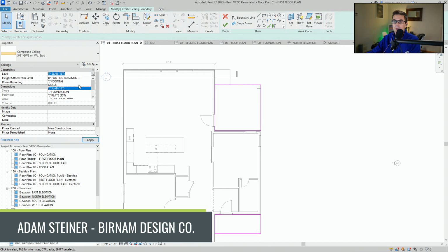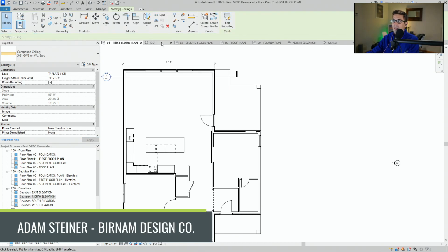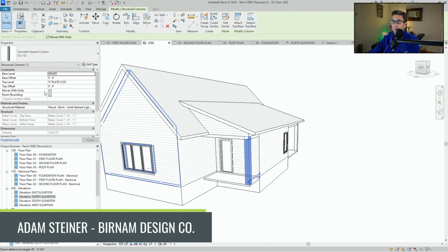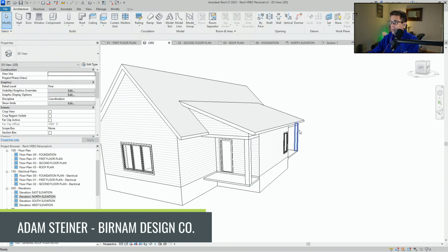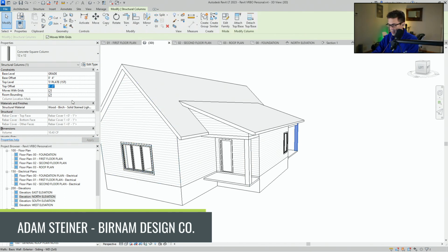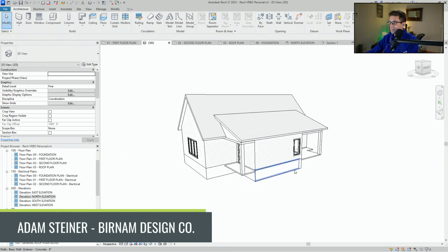And then I want top of plate minus 7.25 inches. Okay. Moment of truth. Oh, cool. Top offset, and we're going to do negative 7.25. And then negative 7.25. Oh, oops. Negative 7.25 inches. Every time with you, Revit. Chill out, man. All right.